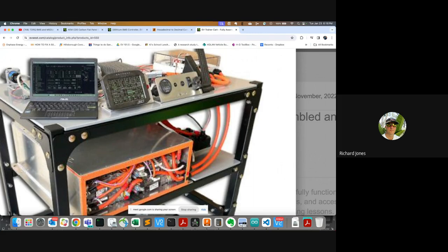Yeah, and there's another terminology just to make that transition. You've seen raw CAN messages, and then we've used a hex editor to figure out a value, and then we happen to know that's the voltage. But when you're working with a tool like the AEM, they use terminology like signals, CAN signals.